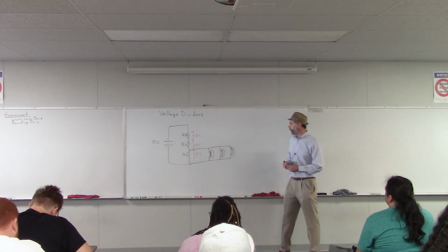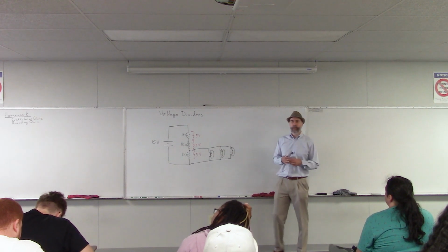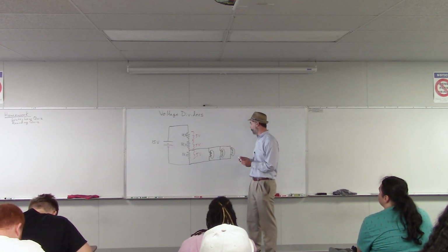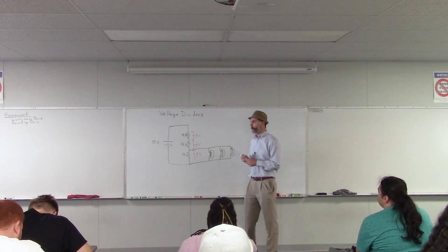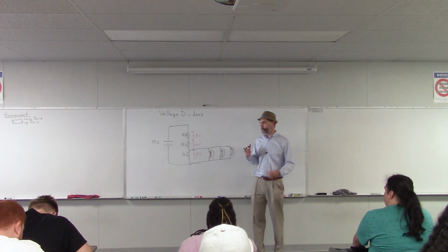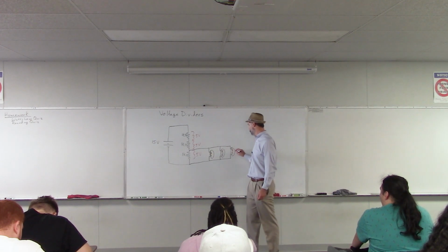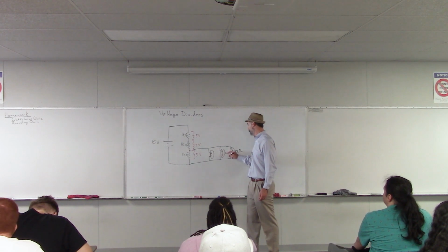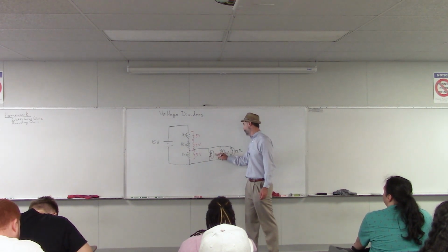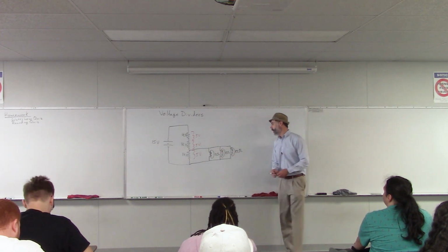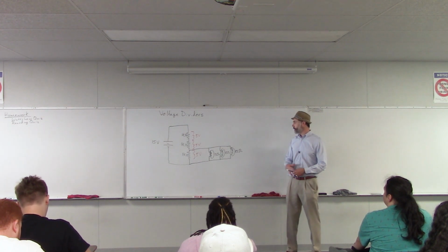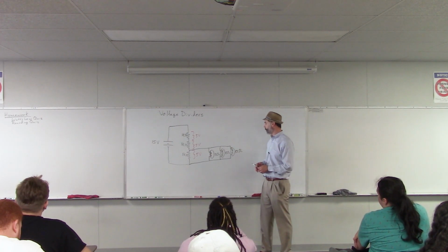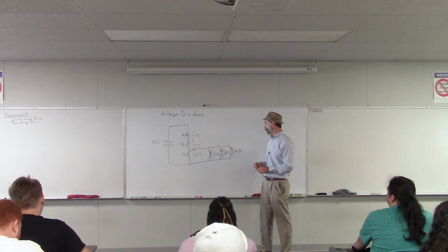And let's think about what would happen there. These light bulbs are like little resistors, and depending on the light bulb, you might have a resistance of, say, 10 ohms for each light bulb. Okay? So now what you've got here is a parallel circuit with 3 light bulbs, and each one has 10 ohms.